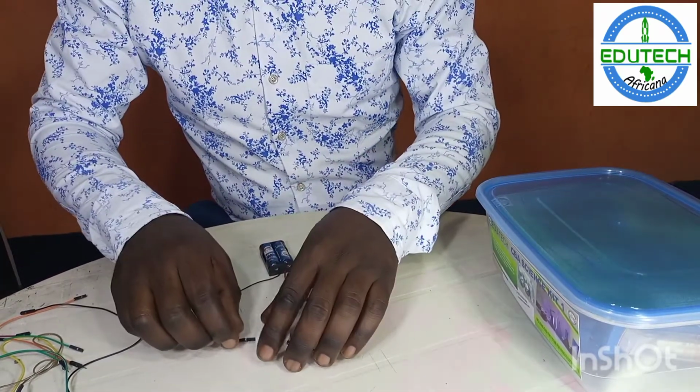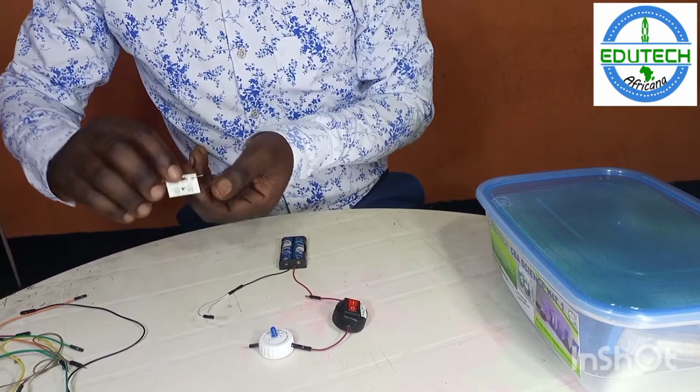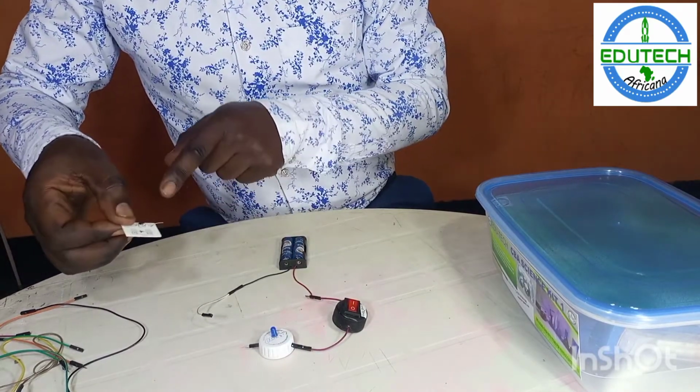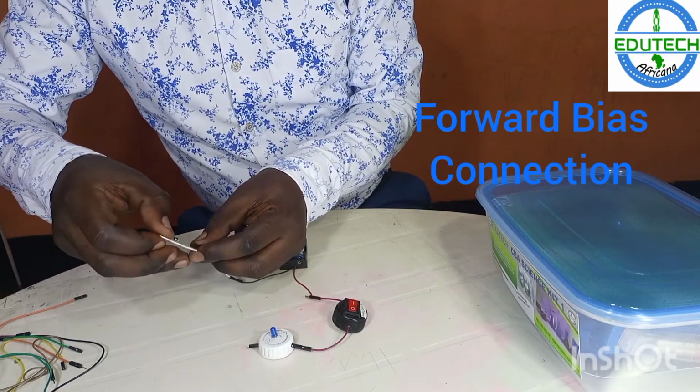So we are going to disconnect our circuit and we introduce our diode. I will start by connecting the negative terminal of the diode to the negative terminal of the battery. This way.